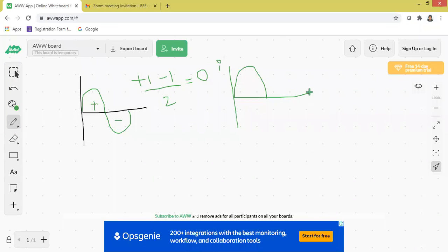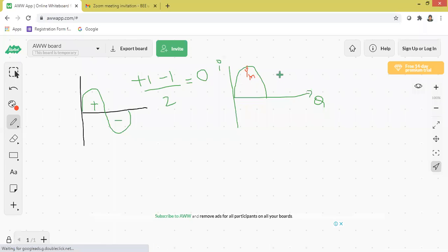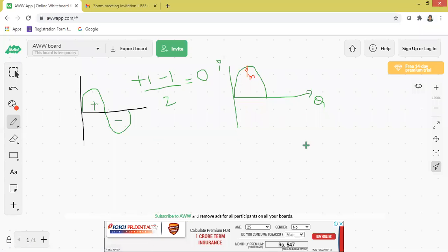Here the x-axis is theta. What we have here is the peak value. Draw along with me. This point is the peak value, which we can write above the curve, or here as Im. Understood? What is the average value of a pure sine wave? Objective type question: it is equal to 0. Average value is explained only for half cycle.